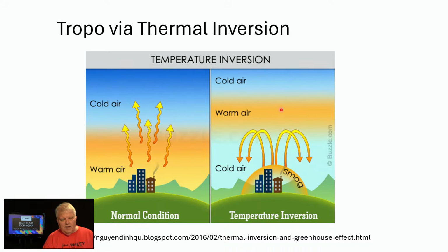This acts as a duct for radio electromagnetic waves. And you can sometimes, typically in spring and fall, you can have long-distance communications for a little period of time on VHF and UHF using this ducting, this tropospheric ducting.